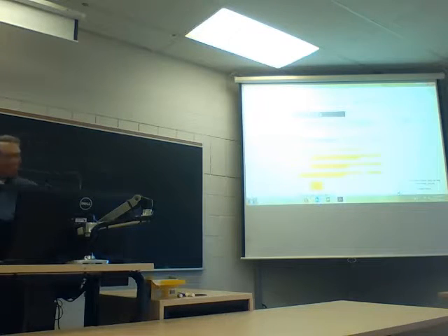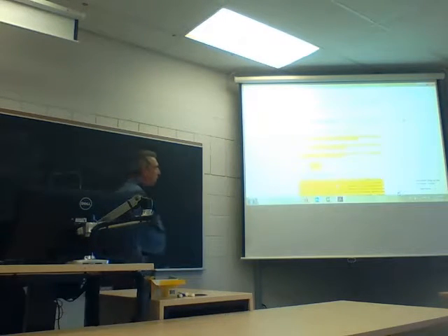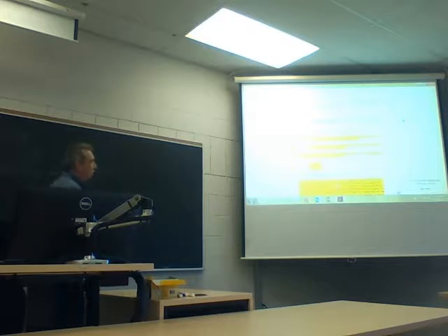All right, rotary compressors. Rotary compressors are classed as positive displacement. Several different designs are used. Most common are sliding vane rotary and rotary screw. They're really becoming popular. They produce a constant flow of air, which is nice.